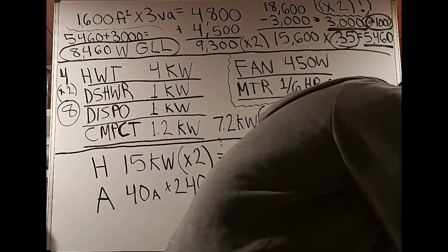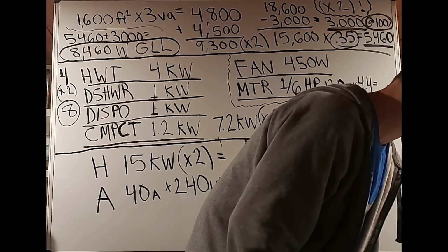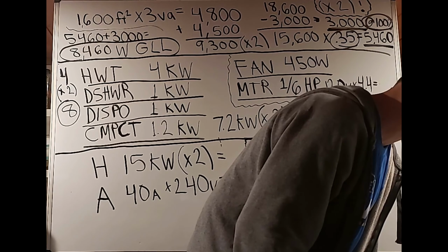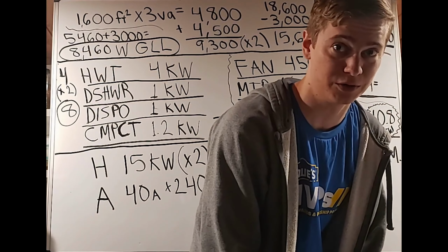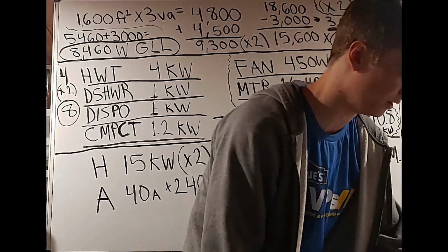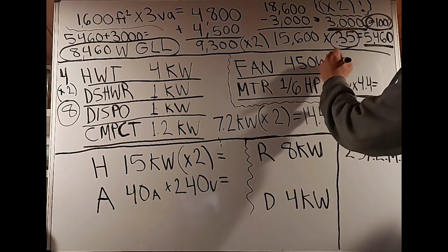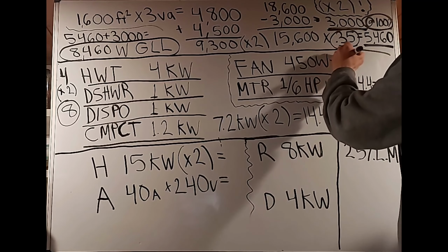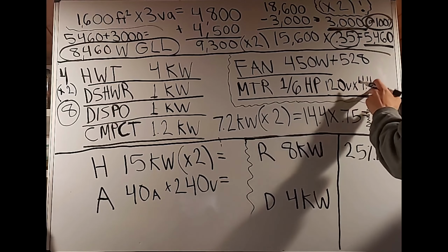So here in Table 430.248, we see we have some different numbers. 115 volts, 200 volts. Well, we're going to have to make sense of this and correspond this to our nominal voltages when we're doing our load calculations. So we're going to get 528. I'm running out of some room, so I'm just going to draw that here. We have 528 watts from 120 times 4.4.